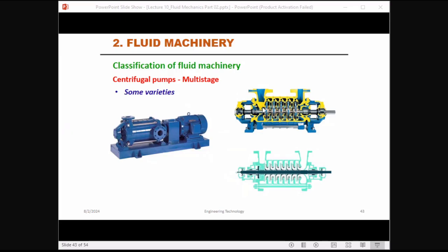The multi-stage impellers are fixed on this single shaft. Each impeller increases the pressure of the fluid, so you can get high head using this pump.